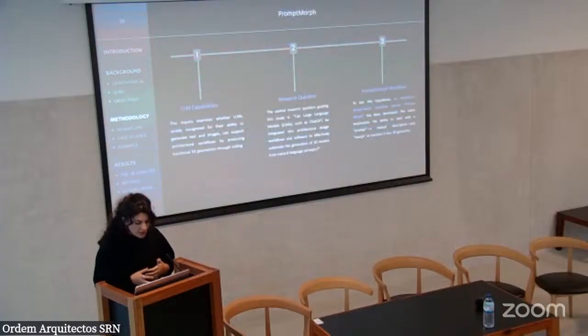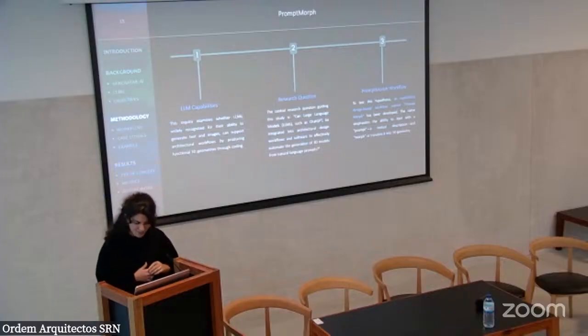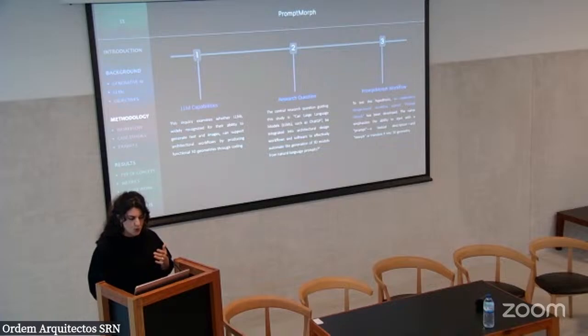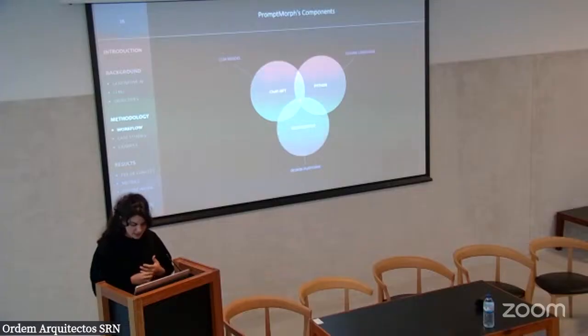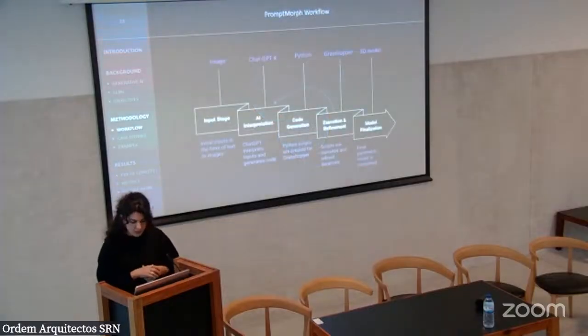So in order to answer this, we have currently developed a workflow. It's quite exploratory and not a proper framework yet, but it works as a proof of concept to prove that this is possible and maybe we need to focus more of our attention on that. How it works is that we're using ChatGPT-4, and we ask it with a certain prompting logic to provide us the Python code that we then copy-paste into Grasshopper, and then we can get fully customizable parametric models.